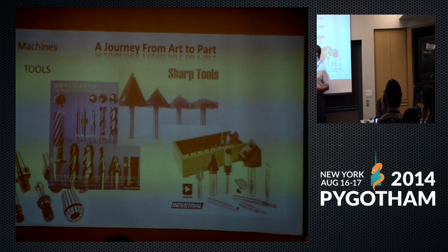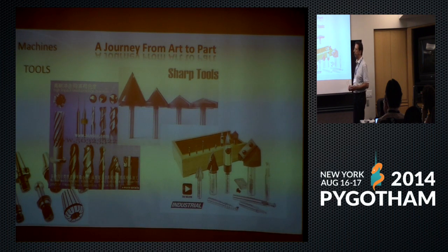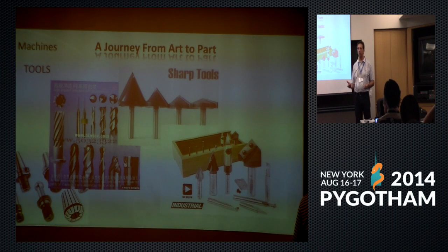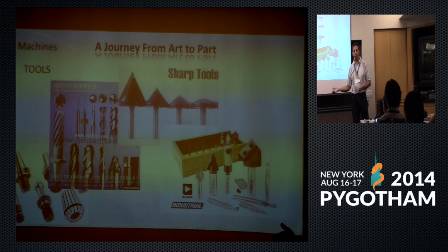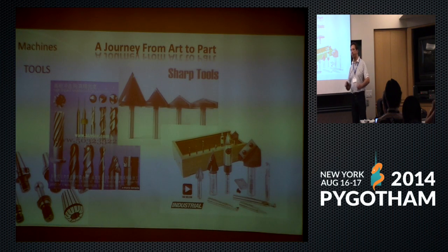You can see you have almost microscopic cutters, which is pretty much used for that last sample I showed you with the wood. And then you have large cutters, which are often used just to plane something or to rough out shapes very quickly. Often this carving is not used just to produce a finished product. It's often used to give you a 70% product, hand-shaped, for example. So you can determine with the roughness of your design how much machine time you want versus manual labor, and where are the benefits back and forth.